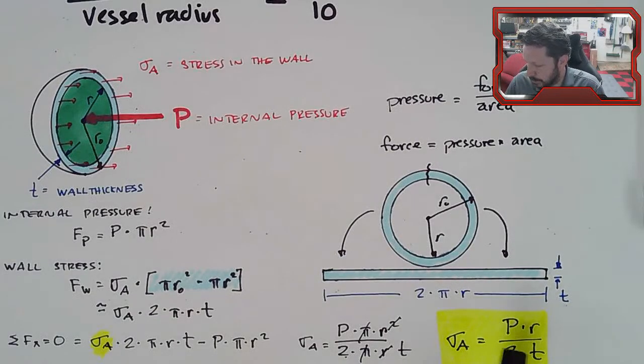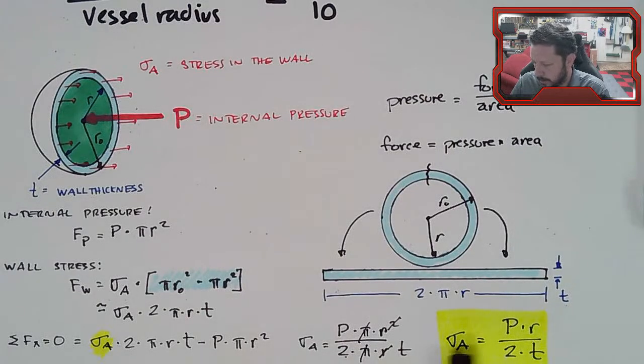So you could imagine using this equation to solve for this stress and compare that to the strength of the material for the pressure vessel. Or maybe you have an allowable stress and you want to figure out how thick the wall needs to be to have a factor of safety. So it's an easy equation to use. We'll use it in a second once we've dealt with the cylindrical pressure vessels. Then we'll come back and actually put some numbers into here.